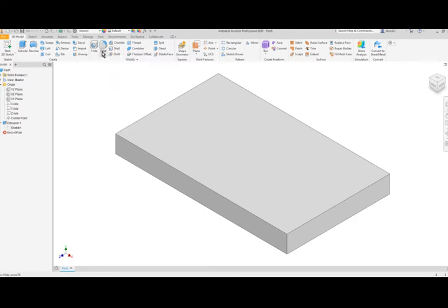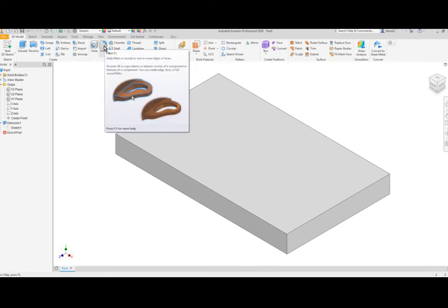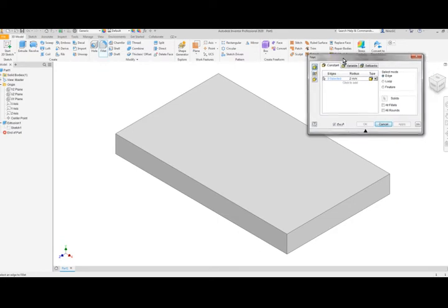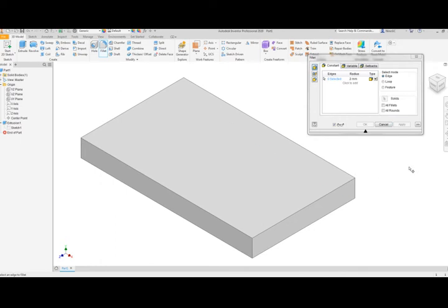So we'll start with fillets. A fillet is a rounded corner. So when I click on fillet, the dialog box pops up and I am able to add fillets. The fillets themselves can simply be, when we click on an edge, we're able to apply a fillet. We can indicate what the size of the fillet is. For example, if I want it to be 5, as I type in 5, the fillet itself adjusts.